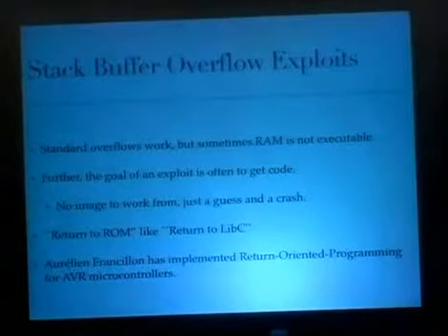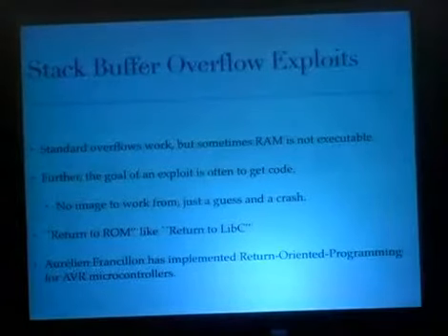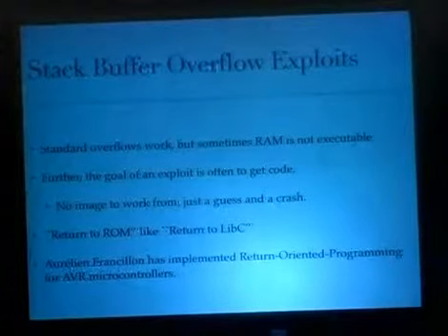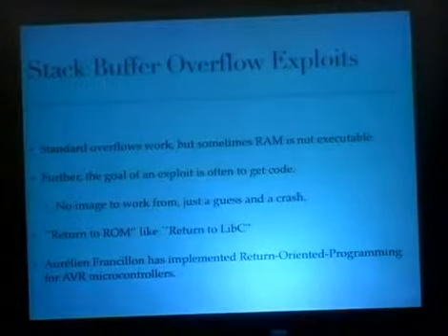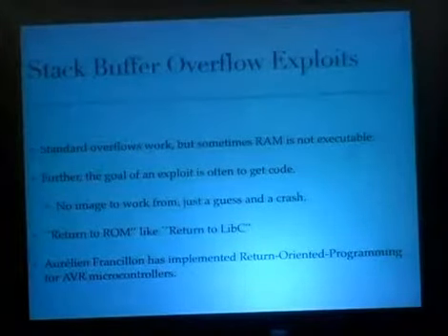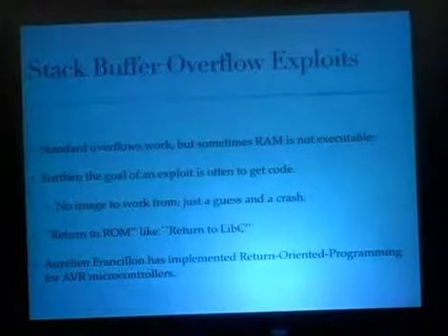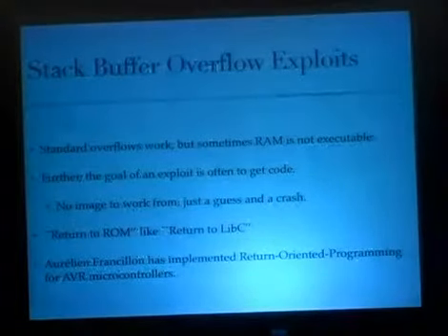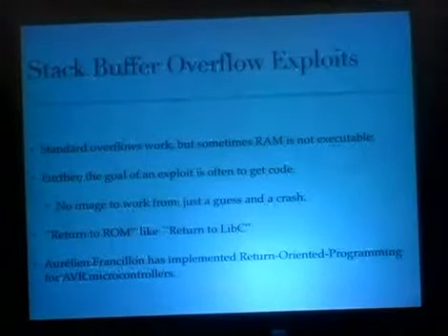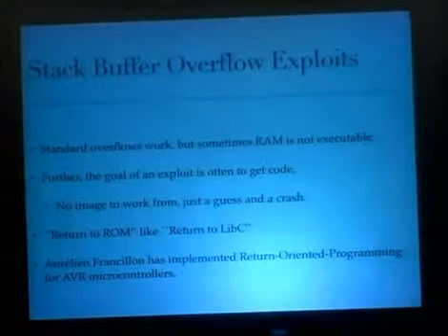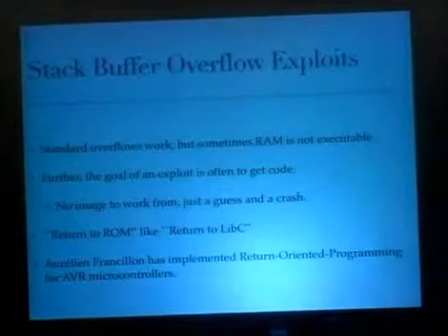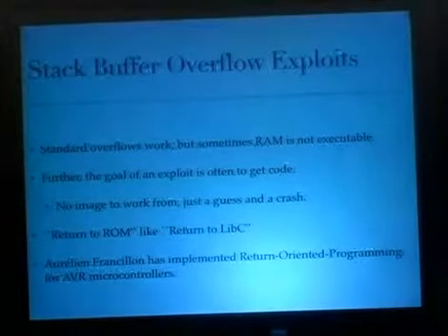Sometimes RAM isn't executable, but that's okay because your real goal is to get a copy of the software out of the chip when you're doing exploits against these. If you're talking to this badge and you're trying to do a stack overflow exploit on it, you would be doing so because you wanted a copy of the badge firmware, not because you were trying to remotely change what the LCDs do. So you can do a return to ROM attack in the same way that you can do a return to libc attack.